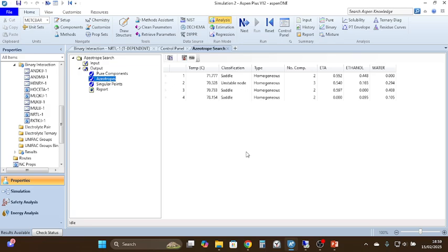That is the separation, or the concentration at which our components will get separated when we are operating from a particular temperature, either heating it or cooling it, or if we are changing the pressure. Okay, so a saddle point in a ternary diagram actually signifies a point where distillation boundaries intersect. Okay, they are usually points of unstable equilibrium.